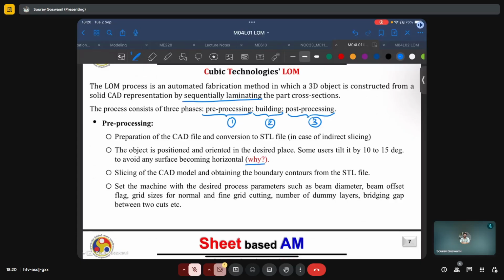The reason it is done, we did discuss in one of the previous sessions, is that we want to minimize the number of horizontal surfaces, because horizontal surfaces, if unsupported, will act as overhang and will require support structures. These support structures, in some cases, may subtend all the way to the build plate or substrate, but in some cases may fall on the part being built itself.